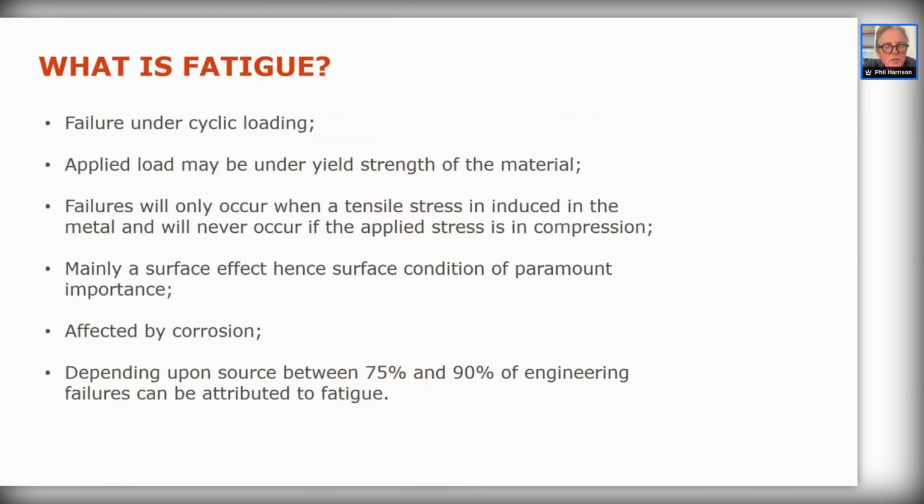Failures will only occur when there's a tensile stress in the material, and never if it's in compression. But quite frequently, if you've got straightforward rotating bending, as in the railway axles, you might be 50% tensile, 50% compressive in the material. The major issue with fatigue is the load cycles which you are using. For example, if you are mainly tensile, for a given amplitude, the fatigue life will be lower than if you are mainly compressive in a material.